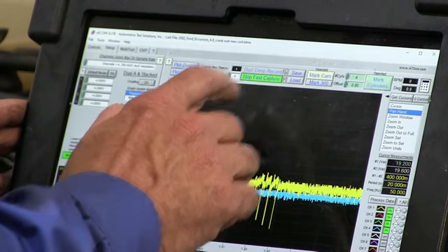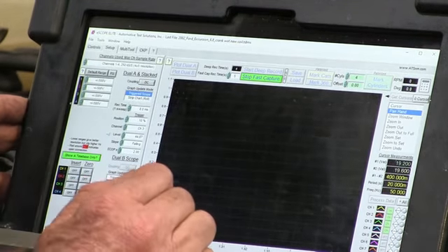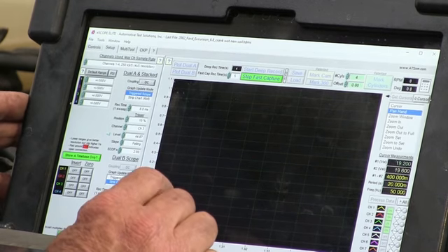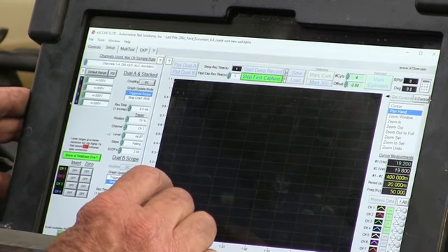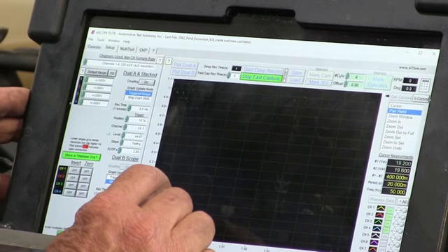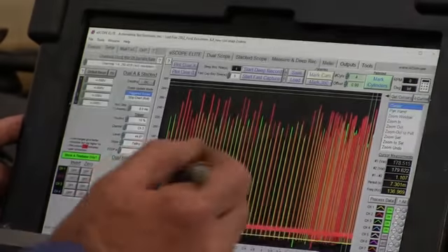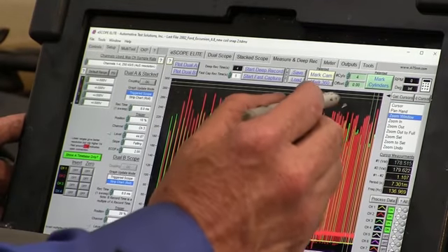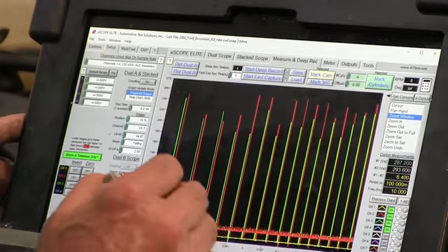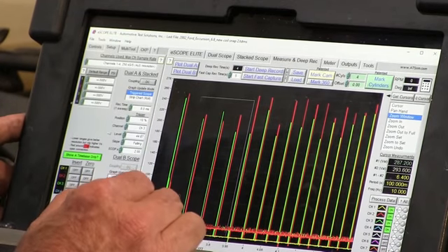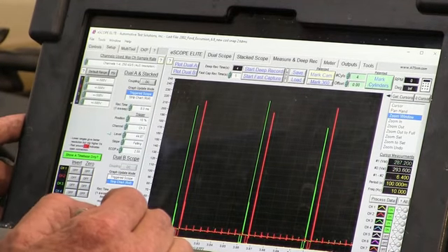So let's go ahead and do a quick snap and see if it's lean, see if 1 is loaded due to it being lean. Go ahead and start it and give me a little snap. Okay, so what we want to do is we want to look right over here. When we first snap, it's the most likely place to find a problem.